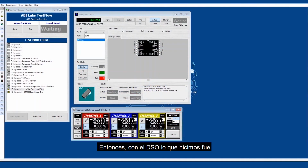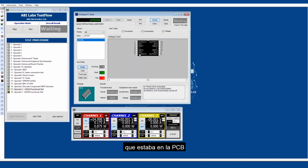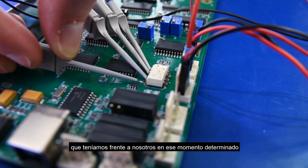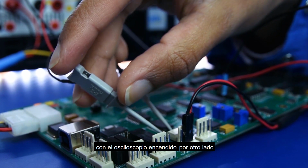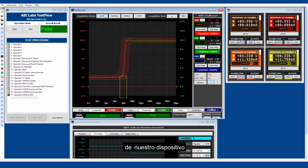With the DSO, what we did was, with the waveform generator, we injected a square signal into one side of the optocoupler, which was on the PCB that we had in front of us at that moment in time. And then with the oscilloscope on the other side, we measured the output and we looked at the propagation delay of our device, and we saw that it switched on at approximately 8 microseconds, which lies within the datasheet. So this was more of a parametric test that we carried out with the DSO and the waveform generator.